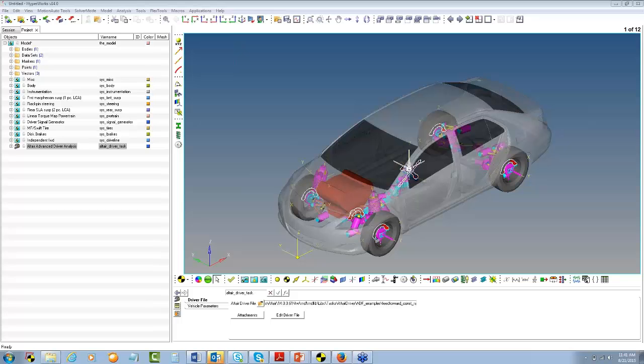You have to quantify that with the tire forces. So your tire limit should be reached. Your tire should totally slip. You might have seen that there is something called longitudinal slip and lateral slip. That lateral slip value should be 100%, and at that point your vehicle should still be on the ground. And if that is the case, then you are fine.